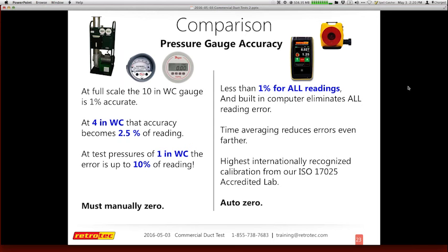And again, the orifices can be plus or minus 2%. Then you add the gauge accuracy at 2 inches of water column. So in general, you can have flows of up to 9 CFM errors over 7%. So those are an additive issue of errors on top of other potential problems you may be reading. And again, also the challenge of going to a flow and calculating all of those.